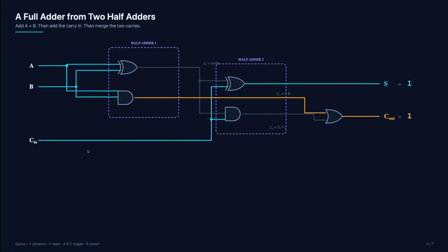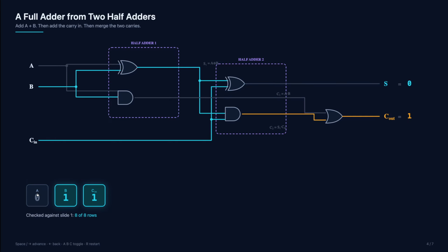All right, so what I've done here in this graphic is you can trace through all the combinations here. Like if I have zero ones here, the output is 0, 0. There's no ones, all right? If carry in is a 1, then what I know is, I have 0, 1, which is binary 1. That works. If I have B equal 1 and Cin equal 1, 1, 0, that's 2, all right? So you can go through here and verify all the elements of the truth table for a full adder and prove to yourself that this actually works.